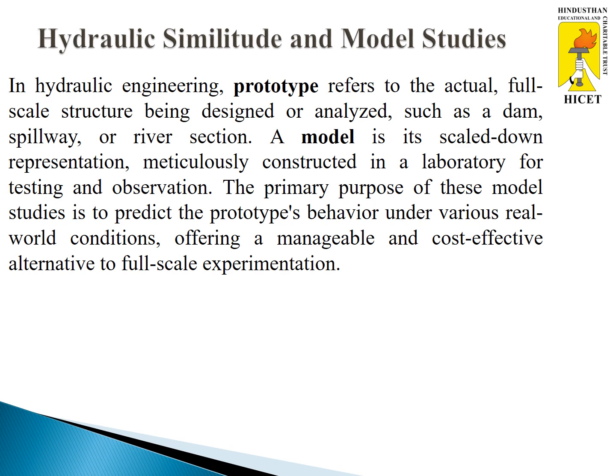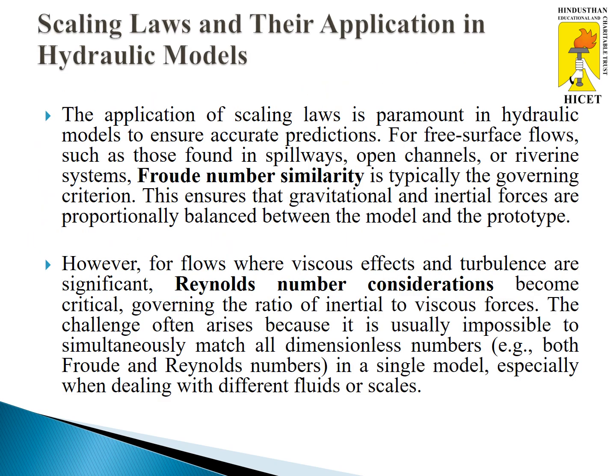Then hydraulic similitude and model studies. In hydraulic engineering, prototype refers to the actual full scale structure being designed or analyzed, such as dams, spillways or river sections. A model is a scaled down representation constructed in a laboratory for testing and observation. The primary purpose of this model study is to predict the prototype's behavior under various real-world conditions, offering a manageable and cost-effective alternative to full-scale experimentation.